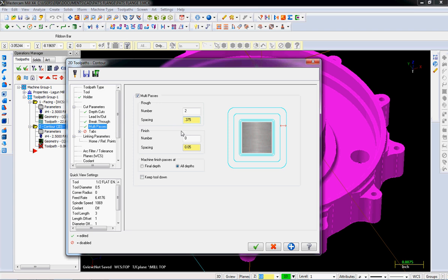One of the things to keep in mind in CNC is just because you can make a pretty picture does not mean it's a realistic cut. You do have to deal with coolant. You have to deal with letting there be space for coolant to get into the cut. You have to let there be space for chips to exit the cut and be washed out by the coolant. If there's not sufficient space, you're going to have a problem. Chips are going to pack, and just because it says CNC in the front of your machine doesn't mean it's going to automatically make the chips disappear. You'll see in the verify there's no chips. It doesn't understand that concept.